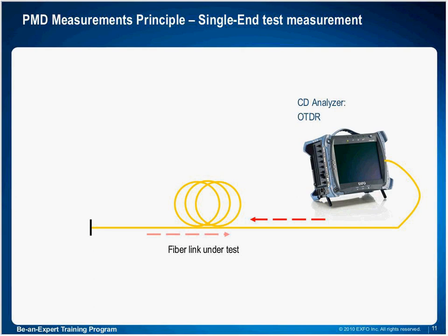So if this module was able to measure anything, it's something that we saw already in the results. It is able to measure the end of the fiber span, which in today's case was located at roughly 17.242 kilometers. So I would estimate that its precision in distance would be roughly plus or minus 5 meters, just like any of our other OTDR test equipment.